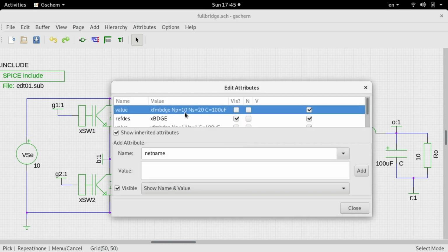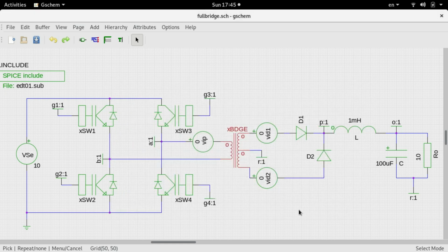So this is your full bridge circuit. You see that I have 10 turns in the primary, 20 turns on the secondary, turns ratio 2. So you will get V pole, here it is 10, so you will have 10 volts at the primary, 20 volts for P, but you will have the diode drops and the on-state drops of the switches. There are two on-state drops, so you will have one on-state drop for switch 1, another on-state drop for the other switch S4, which will come into the picture. Then you have the diode drop, so you probably will land up with around 3 to 3.5 volts drop overall, so you may have some 16 volts at pole voltage. Then the duty cycle and output voltage comes in here.